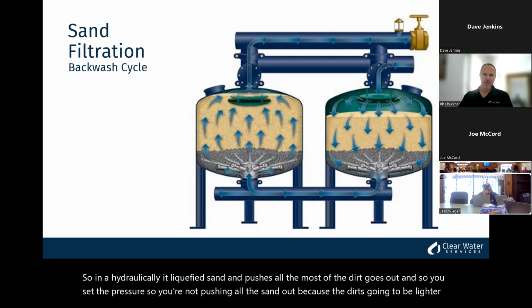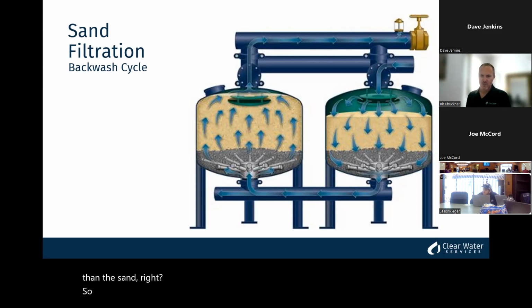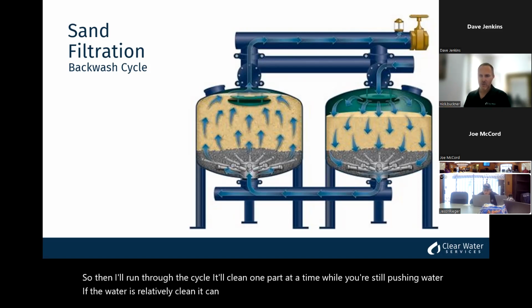Then it'll run through the cycle. It'll clean one pod at a time while you're still pushing water. If the water's relatively clean, it can still discharge. Sometimes it'll spike and have to go into recirc for a little while you're doing the backflush cycle.